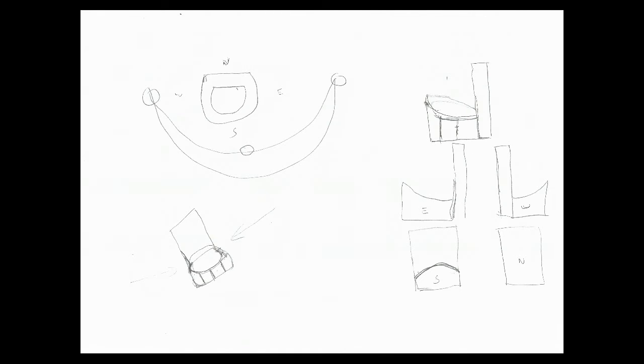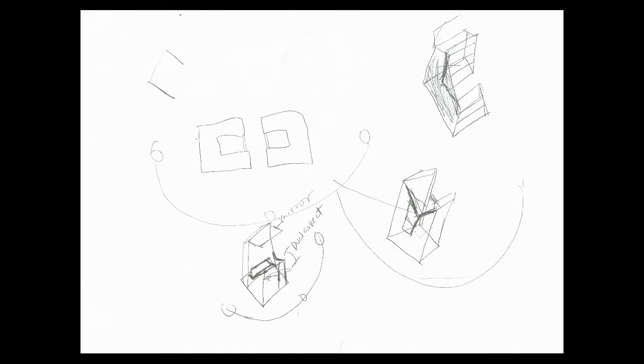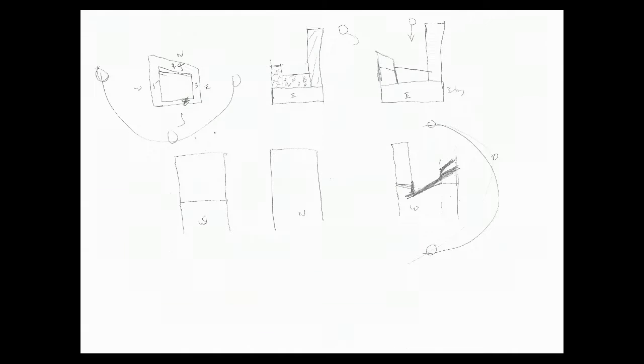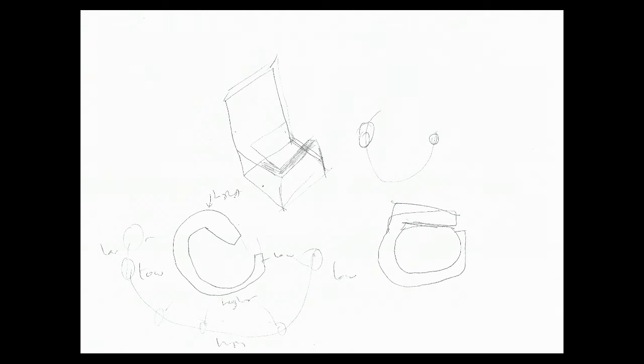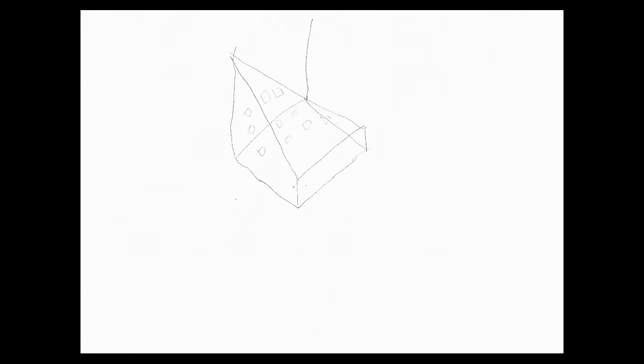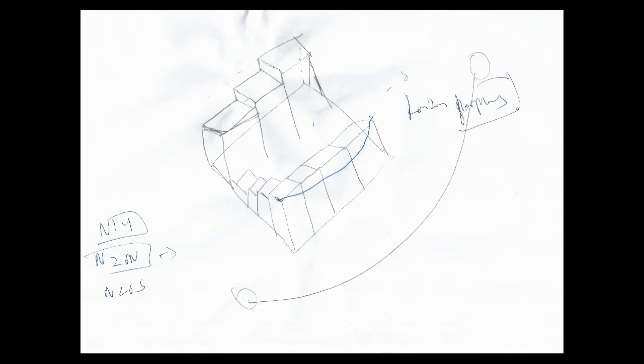The initial point of the design process was the formation of conceptual ideas. Sketches were done to experiment with the shape, forms, and angles. The sketches helped to show how different forms could deal with the sunlight, wind, and human scale. But they also gave ideas relating to how the buildings will look and how easy or difficult it will be to build the different forms on the site. A rectangular form with tall and narrow portions towards the north, and shorter buildings towards the east, west, and south could probably be sunlight and wind efficient, help to achieve human scale, be practical to build, and also look relatively good.